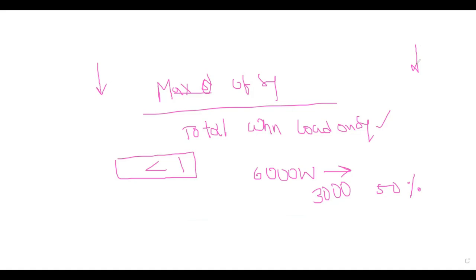For a simple example, say I have a shop which has one fluorescent fixture of 5 kilowatts, and some sockets with 1500 watts, and one air compressor, and a pump for the fire pump, which is, let's take a 15 HP fire pump.